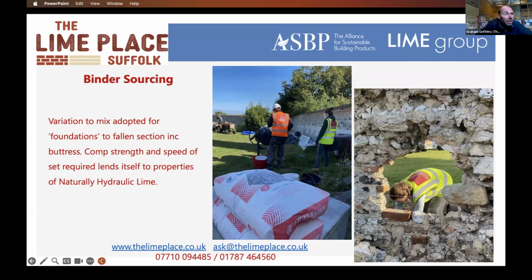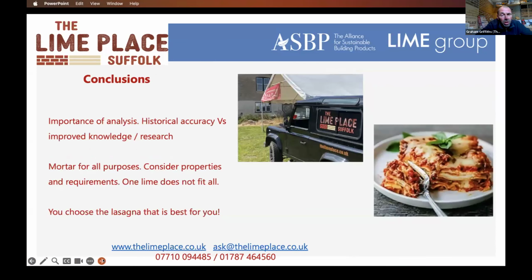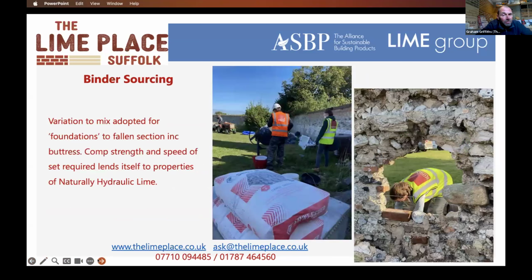So the analogy here is along the lines of using a prepared sauce and a prepared pasta sheet. So we're using a product that is convenient, has been tested. We know what the outcome is going to be because we've seen it before. Some of the purists might say that we could have used a pozzolan. We could have done, but it would have just been another batch of sourcing another material, testing it, checking the ratio, doing samples. So what we used there was a material that we had that was the right one to be used in our opinion.